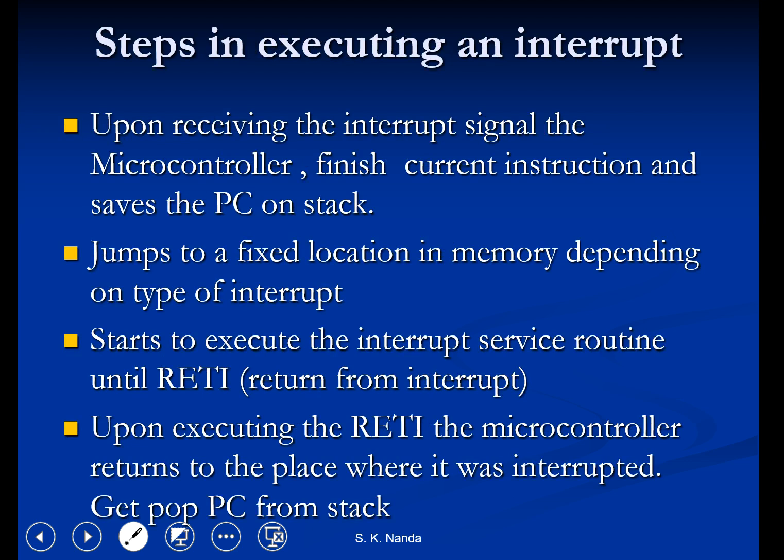Upon receiving the interrupt signal, the microcontroller first finishes the current instruction and saves the PC on stack. Then it jumps to a fixed location in memory depending on the type of interrupt. Then it starts to execute the interrupt service routine until RETI, that is return from interrupt, is raised high. Upon executing the return from interrupt, the microcontroller returns to the place where it was interrupted. It pops the PC from the stack to find out its last location.